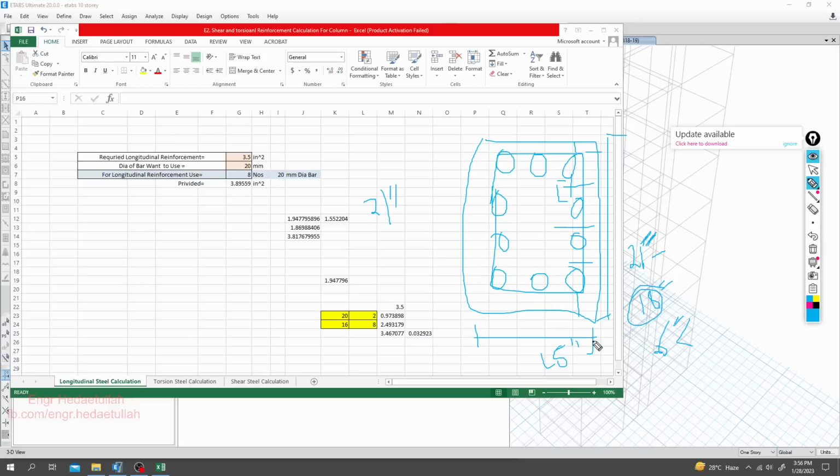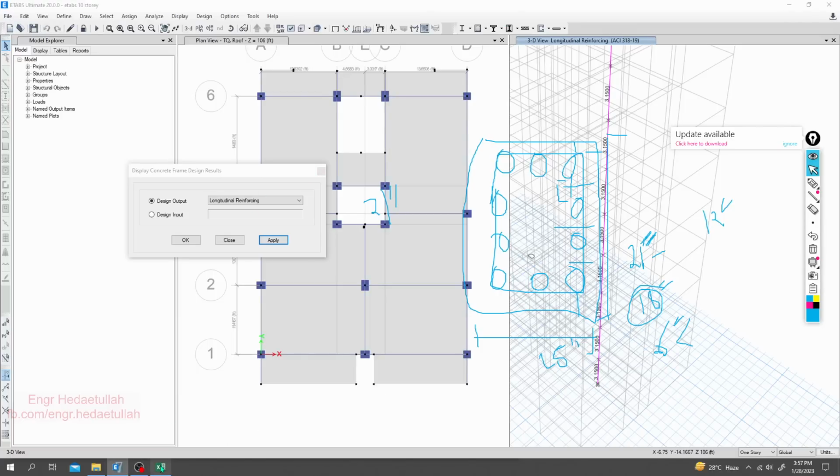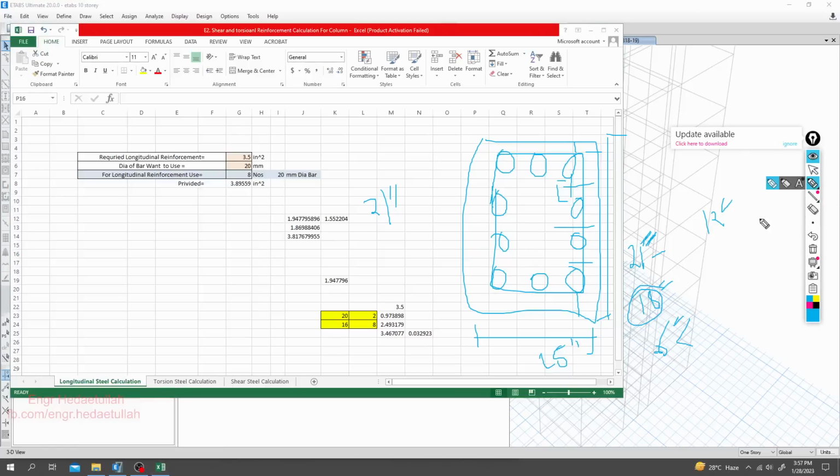if we subtract the clear cover, then it will be 12 inch. So if we get that value as 12 inch, just one thing I'll check here again. Okay, it's okay. Then what will be the value of it? Here 1 and 2, and also you have to remove that dia bar and then the stirrup dia bar, so it will be okay. Actually, in this way you have to maintain the minimum and maximum spacing of that reinforcement.